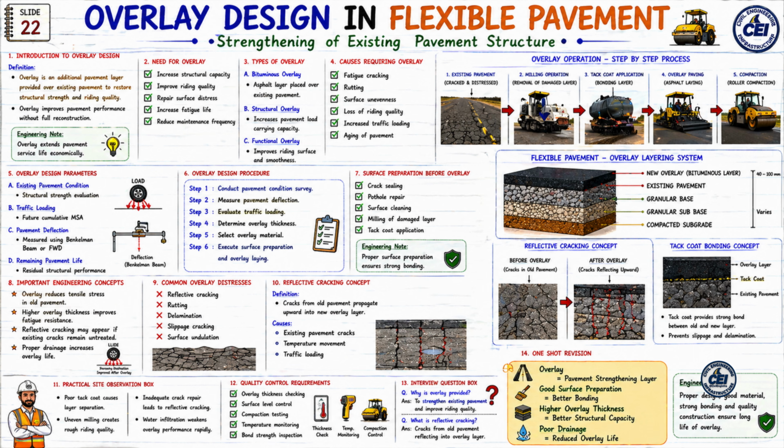Now let us look at the tack coat bonding concept. Tack coat provides a strong bond between the old and new layer and prevents slippage and delamination. If the tack coat is not proper, the overlay may fail quickly.